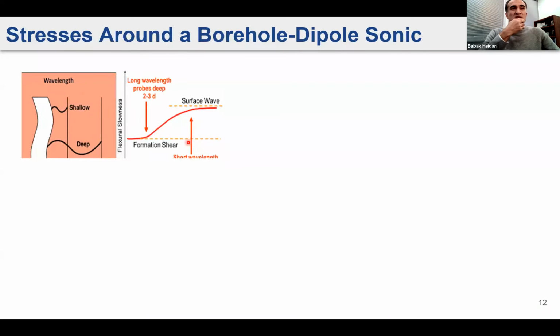We know that the dipole measurement gets polarized and has dispersive behavior, so based on different frequency it has the capability to probe into different depths of the formation. These are the fundamentals around the dipole shear sonic measurement.